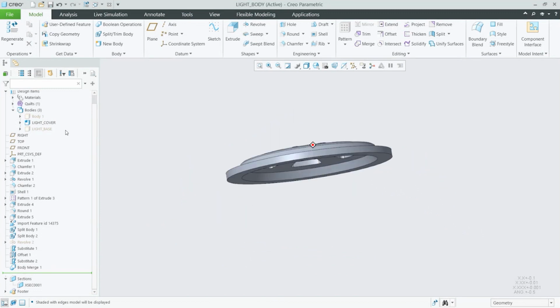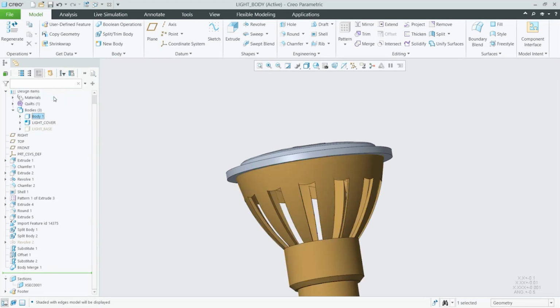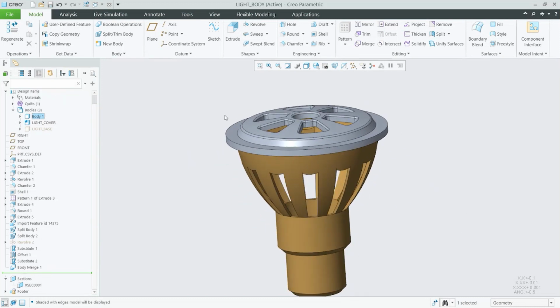So this is one of the areas of the power of flexible modeling. Now, many people say that flexible modeling is only applied to imported features, no history based features. Can I apply flexible modeling to a history based part? For example, a Creo feature created part. If I use Creo, using parent and child, using features, I get a parent and child relationship. I can simply modify the dimension. So why do I still need flexible modeling?